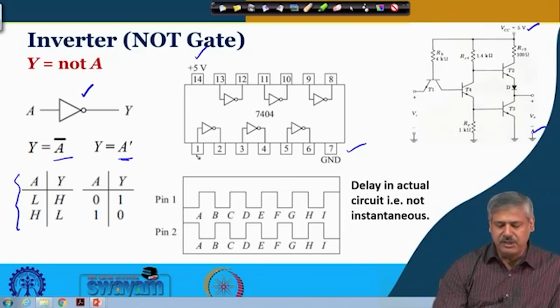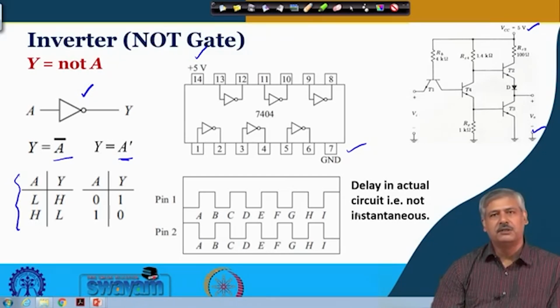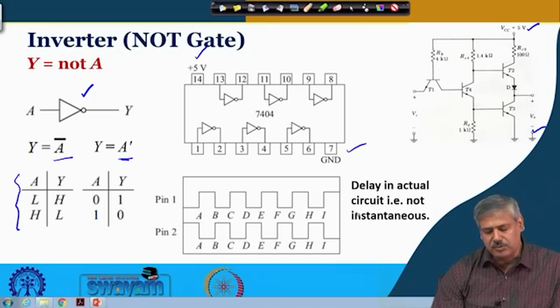And if we give at the input of pin 1 a signal which is low and high, 0 volt, 5 volt, just a rectangular signal like this, then what will happen at the output? Whenever there is a low, there will be a corresponding high at the output. So, this is pin 1 and pin 2 that you see, okay, and that way it will continue, right. Depending on how long the input signal is changed, you will see a corresponding timing diagram at the output.